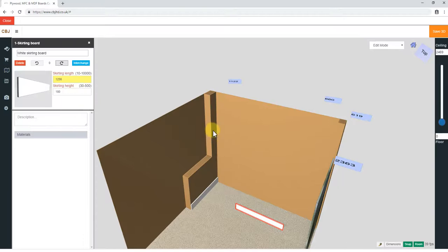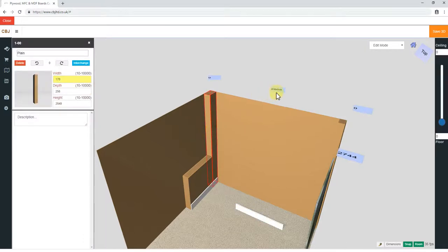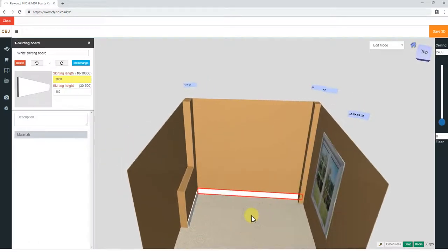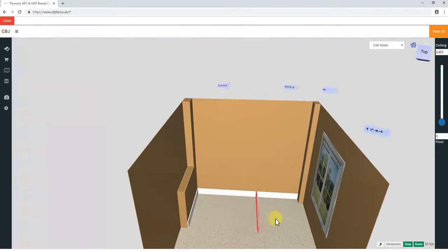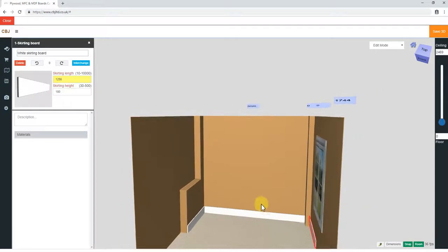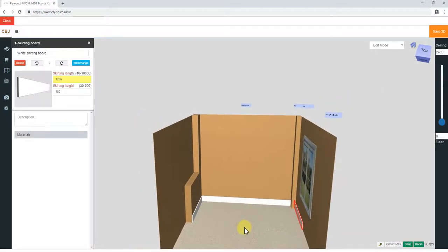Now the width of this wall, so I know, and it's clearer, 2868. So my length is going to be 2868. And again, I want it to be 170 millimeters away and 0. That's it. The skirting is in. I could do bit by bit around the pillars if I want to, but most of the time it's not that necessary. So I can just bring in another one and position it up against here. That's it. Our room is done.